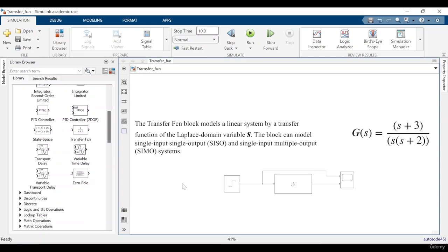Let us understand how the transfer function can be used in automotive applications. Suppose we are developing the system for the power window of a car. The user requests to open or close the window, or gives a request to set a target position of the window. In that case, we cannot change the window position suddenly. The window movement should be done smoothly. The transfer function is used to reach the target position effortlessly.